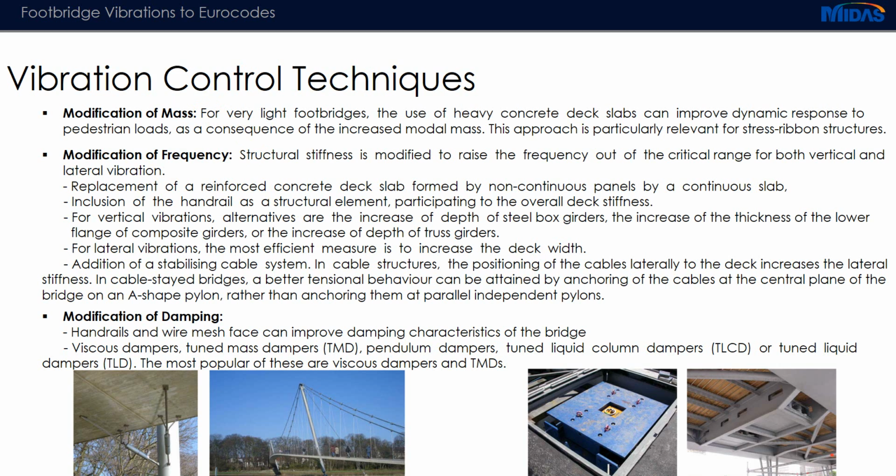As mentioned earlier, for very light footbridges, the pedestrian load tends to act as a mass and can lead to a lower frequency of the structure. So we need to use heavy concrete deck slabs, which can improve the dynamic response of the structure. This is very commonly used in stress ribbon type of structures which have a light deck and a central spine, so we make it heavier by using deck slabs.